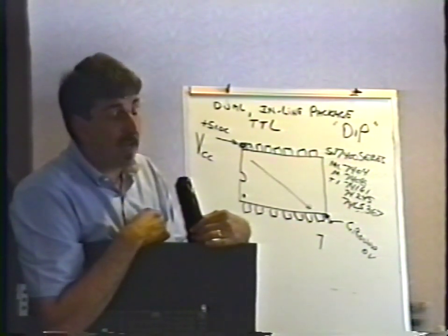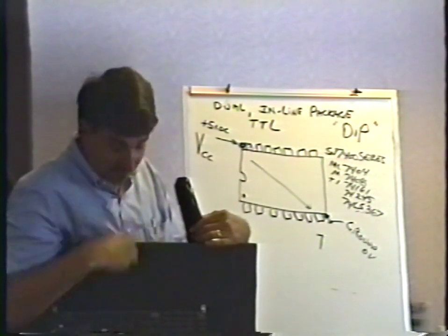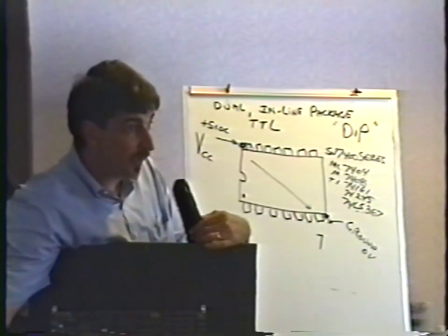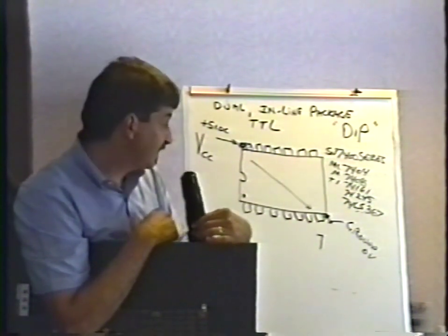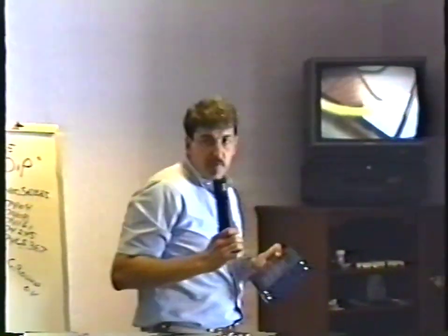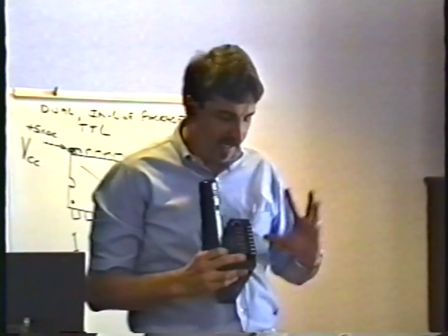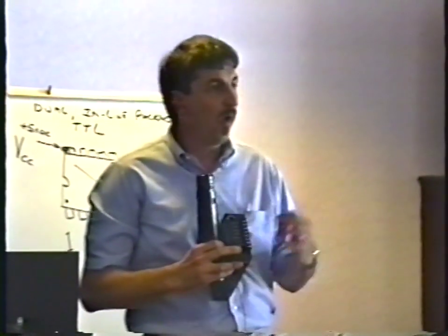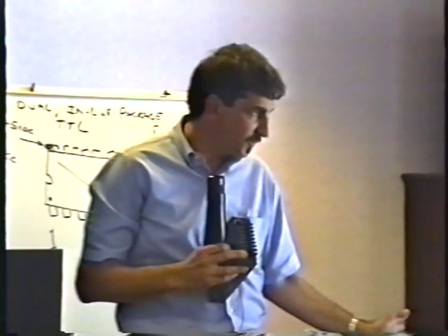Now, I've got to admit that I don't do this. I really don't, because most of the time when you have problems like this and the 5 volt test's okay, it is the board that's bad. But sometimes it's the power supply and you can't figure it out. And since there are only a few screws on the power supply, you don't even have to mount it. It's not a bad idea to take another power supply, just move all the wires over from one to the other, and try the new power supply first.